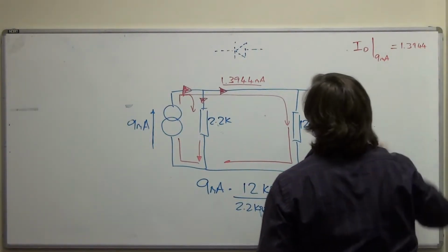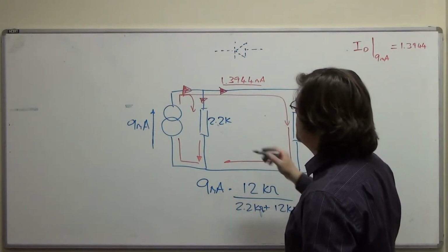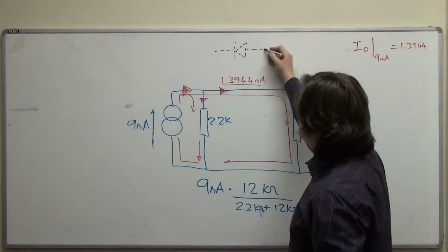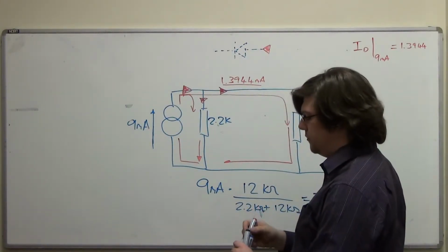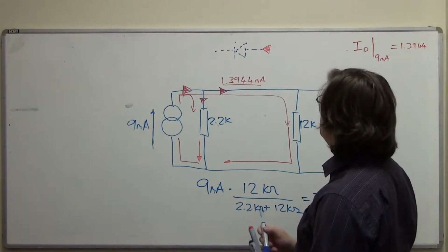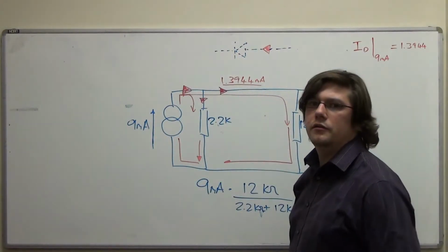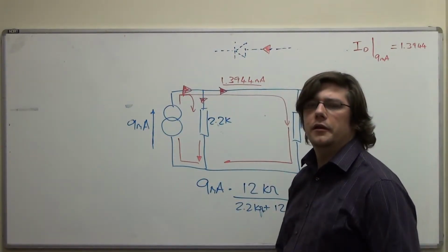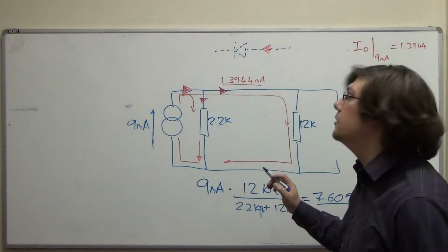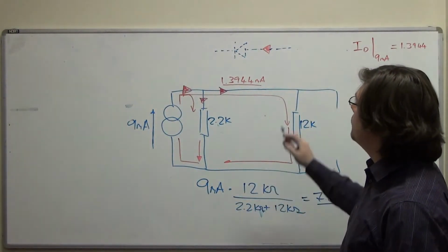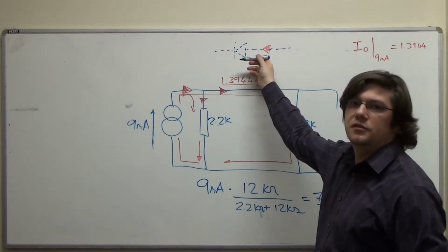And the other thing we've got to remember is what direction it goes in. Now, it's up to you, but I would say that the current flowing in the diode is positive as far as I'm concerned, because this represents an anode to cathode current for a forward biased diode. And we know this diode's switched on, which means it's forward biased, so we know that ultimately we must find a current that's going that way and has a positive sign.